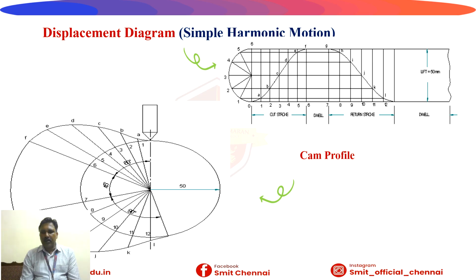Everything we have to take in the compass, and gradually we take the intersection arcs in the cam profile. Already we marked all the angles, the displacement, and the split up of angle. In the split up of the angle, we have to take all the distances in this cam profile diagram. The same thing should be followed in the return stroke also. Take the intersection in the corresponding split up of the angle.